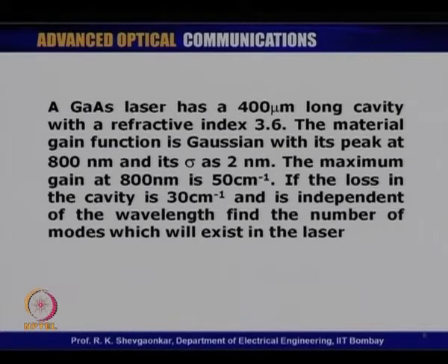As we know, inside the laser, the gain function is a frequency dependent function, but the losses which take place inside the cavity, normally they are frequency independent. And as we know, inside the cavity, the two mechanisms operate simultaneously. The photons are generated because of the gain function, and the photons are lost because of the other loss mechanism inside the cavity. It is the net gain between these two which decides whether the mode will go into the oscillation or not.